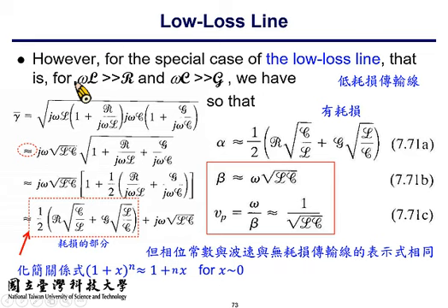So if you take a sneak preview about the result, once the assumption of low loss transmission line is true, then here is the phase constant, beta. Well, it's actually nearly the same as the one of lossless transmission line. It's the same as omega times square root of L times C. Here is the propagation velocity. If it's a lossy transmission line, the propagation velocity is a complex number. Can you imagine the implication of that? No, it's probably hard to imagine, right? Hard to describe.